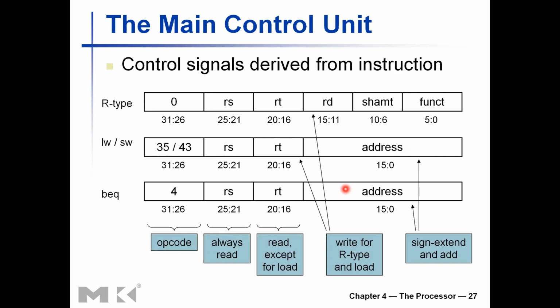That is called the decoding of the instruction. So based on the opcode and the other parts of the instruction, you should treat them accordingly. Immediate offsets in the instruction should be sign extended and added on top of a base register address.